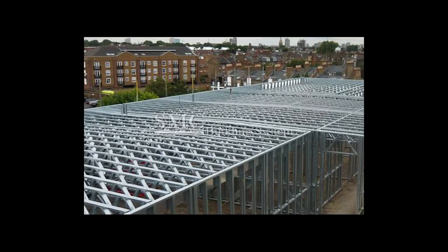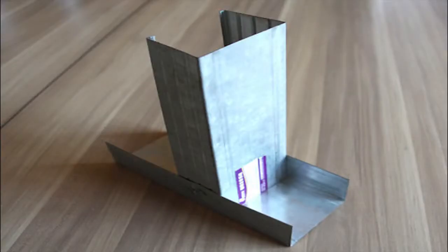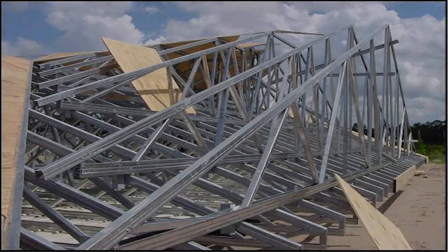Nowadays, it is preferred over wood because it costs less, it has rot and termite resistance, it is easy to work with, and it doesn't require any special equipment. Another advantage is its strength, which gives it a long lifespan. Light gauge steel is easy to form in different shapes to carry the components, and it can be insulated by a large range of materials. It is also non-combustible, but fire protection should be provided because it quickly loses its strength in fire.